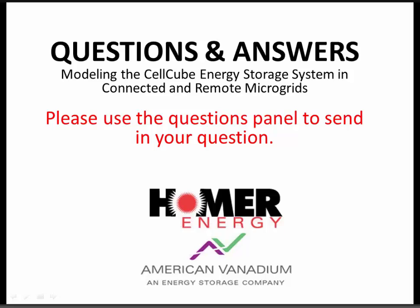Someone asked, how do you deal with the limited temperature range that vanadium batteries tend to have? What are you doing to optimize the batteries? Okay, well, once again, when you say limited temperature range, you're really talking about the electrolyte, and its operating range is between 0 to around 40 degrees centigrade.